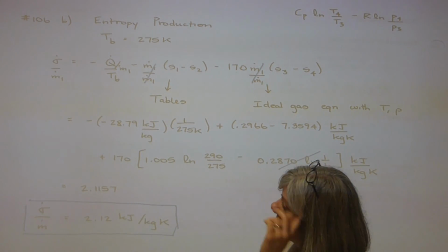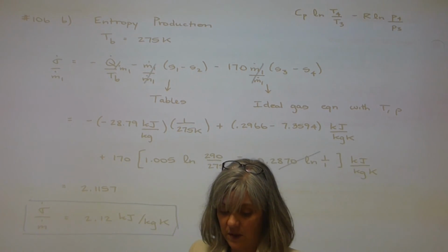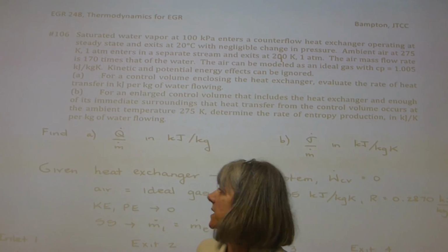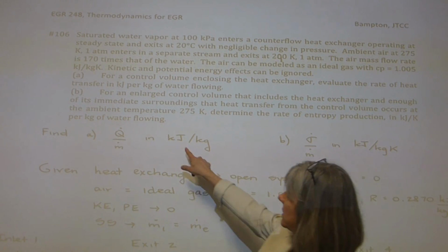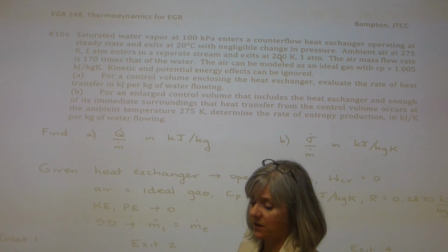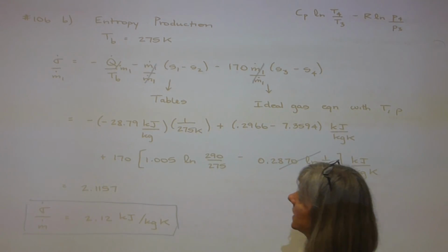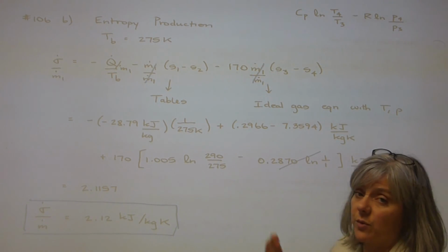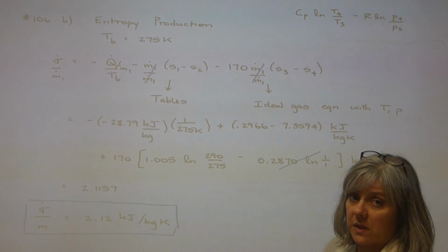Okay, so again, pretty straightforward. Some of this was review, particularly looking at just open systems like this. That should feel comfortable. Again, the kilojoule per kilogram, that's a slightly different setup that now we know how to handle. And then what's new is looking at entropy production. We have an entropy rate balance equation and an entropy balance equation for closed systems.